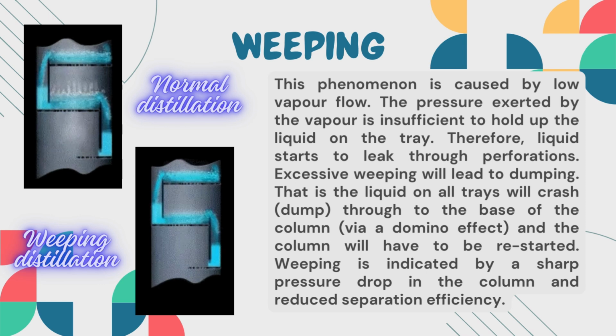So guys, to summarize in simple words, you all know that distillation is a process which works on the principle of vapor-liquid contact. The better the vapor-liquid contact, the more separation will be achieved. And weeping is a problem related to this vapor-liquid contact. Weeping is a phenomenon where the vapor pressure is low in the column, due to which the liquid held on the trays comes down because of the low vapor flow rate and drops onto the next tray and disrupts the vapor-liquid contact, and this leads to less separation efficiency. Okay guys, so this was in brief about weeping.